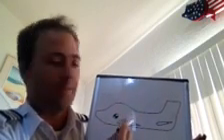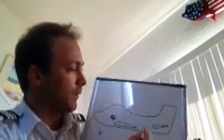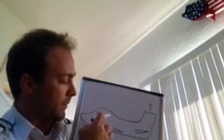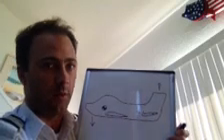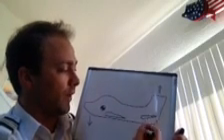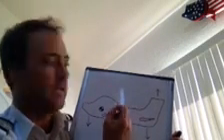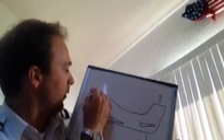of pressure. So what this means is we always have a nose down force, which is going to create a seemingly tail up force, simply because we can imagine this pivots about the center of gravity. So what we have to do is have the elevator and horizontal stabilizer mounted to the aircraft. Its angle of incidence is already predetermined by the manufacturer with a tail down force to compensate for that. And this force can be seen as a nose up force.